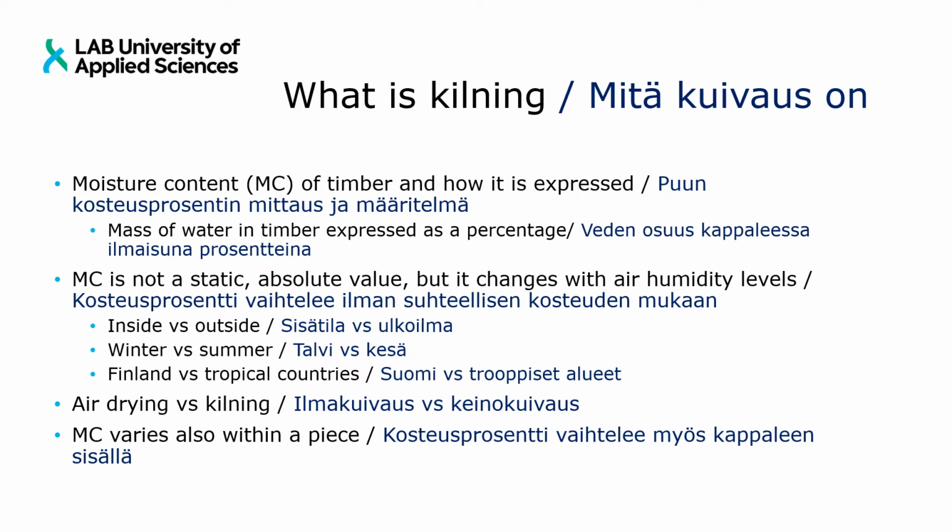As an example, in Finland, when we have the heating on more in the winter time, then the timber used inside in the paneling and in furniture tends to shrink. If you have tongue and groove paneling, that tends to shrink, and if it has not been pre-painted, you will see little stripes over there. And then conversely, when the heating is taken off and the humidity in the room increases, then the pieces of timber expand.